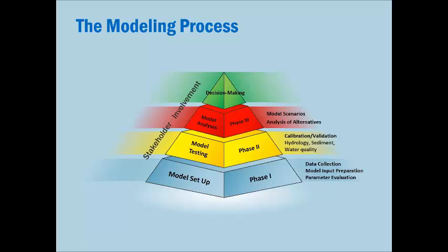That's where you go through a process of calibration, adjusting model parameters during the calibration phase and comparing model results for an extended period, typically 5 to 10 years of calibration, adjusting the model parameters to get the best fit you can during that period with the observed data: the full range of flow values, annual values, monthly values. And then looking at the sediment information you have and trying to represent sediment concentrations and loadings and water quality.